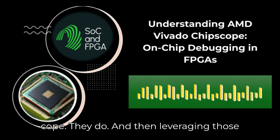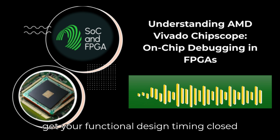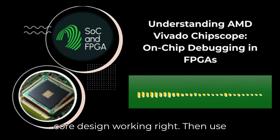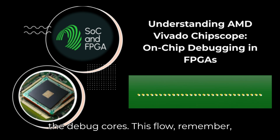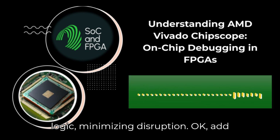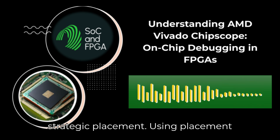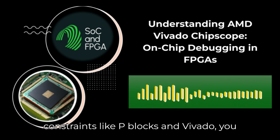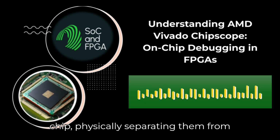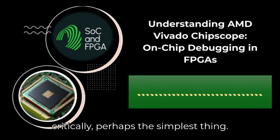They do. And then leveraging those iterative and guided implementation flows is key. The best practice is usually to get your functional design timing closed first without any debug cores. Get the core design working. Right. Then, use Vivado's incremental compile flow to add the debug cores. This flow, remember, tries hard to preserve the existing placement and routing of the functional logic, minimizing disruption. Okay, add debug gently. Exactly. You can also use strategic placement. Using placement constraints like P-blocks in Vivado, you can guide the placer to put the debug cores in less congested areas of the chip, physically separating them from known critical timing paths. Manually guide the tools.